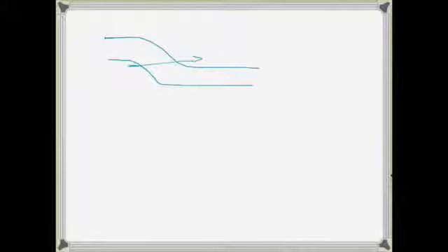And so, for that to happen, in the extreme case, when you have a very high electric field here, there can be a lot of states in what you would consider to be the band gap, because they're tunneling into it. Right? The states are tunneling into the band gap, and it's no longer clear that you can just integrate right to a band edge.